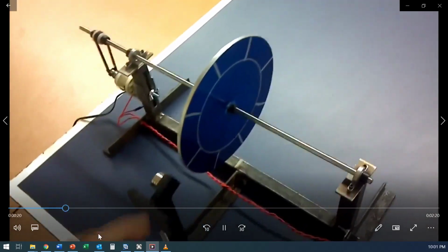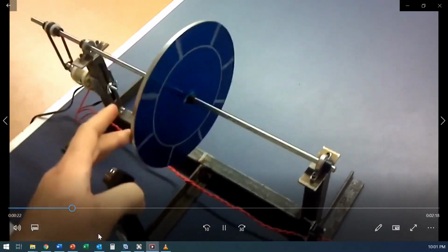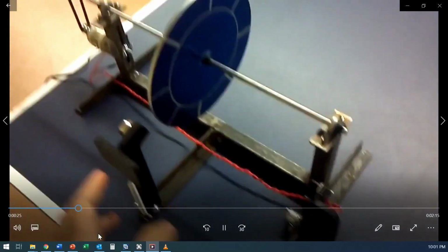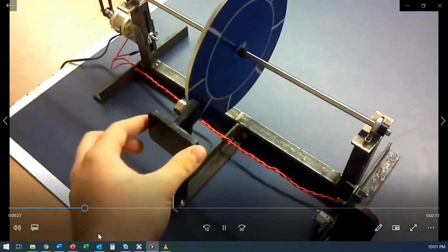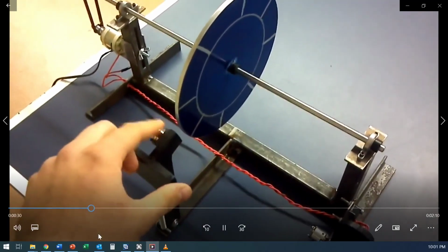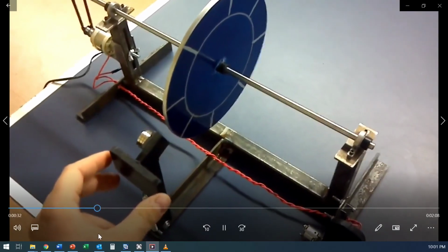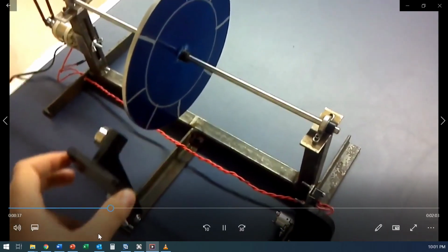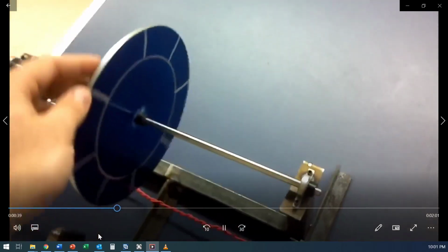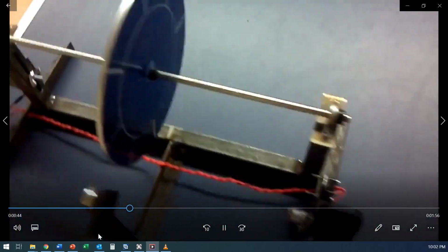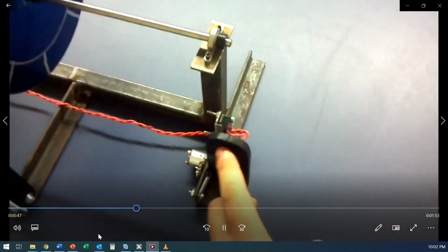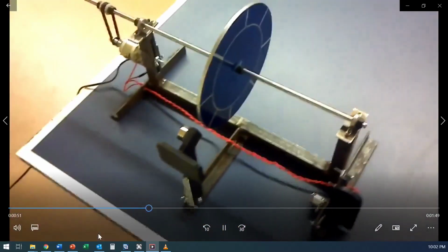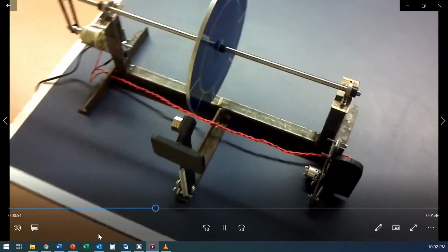And as you can see, there's an aluminum rotor here, and being aluminum it is non-ferromagnetic. And on the end of this representative brake pedal are some very strong rare earth magnets. And as you can see, if I hold it over here, there's no attraction between it and the rotor. The rotor spins on this axle, which is driven by this electric motor, which in turn is powered by this representative pedal. Now obviously this wouldn't be how it's set up in an actual vehicle, but this is just to demonstrate a purpose.